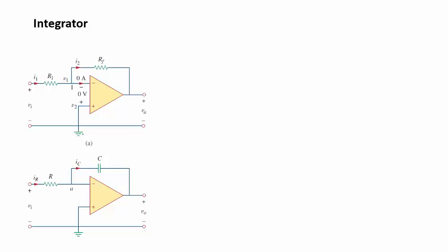It's the same thing when we have a capacitor in the circuit. So the voltage at that node is the same as the voltage at that node, and this non-inverting node has 0 volts in, it's tied to ground. Therefore, the voltage at node A is also 0 volts. And no current is going into this terminal right here.